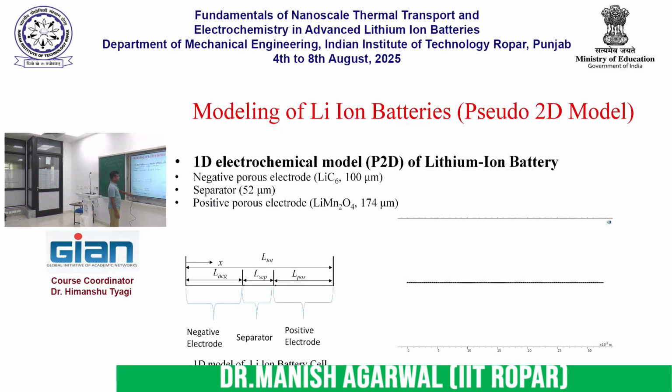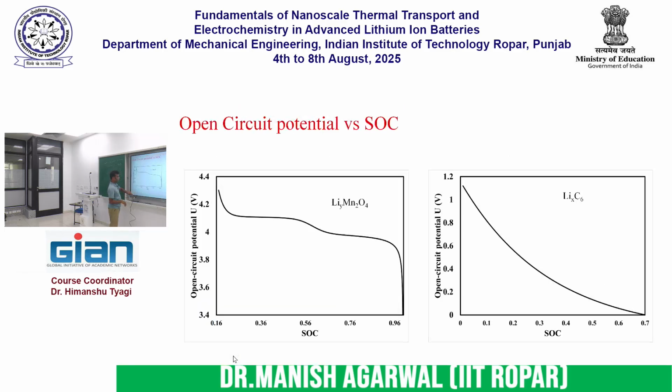So he has taken lithium, I think graphite, as the negative electrode, and manganese oxide as the cathode, and this is showing the open circuit voltage as a function of the SOC, how it is not constant. When it is fully charged, it's 4.2. So here it is SOC equal to 0 at the positive electrode. At the negative electrode it is SOC equal to 1, so the open circuit potential is going to be 0.